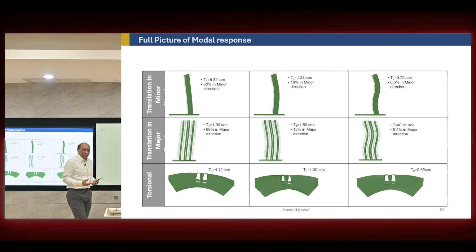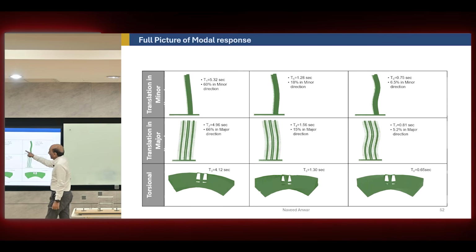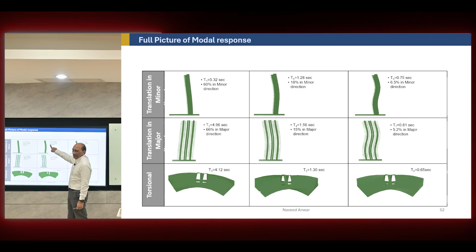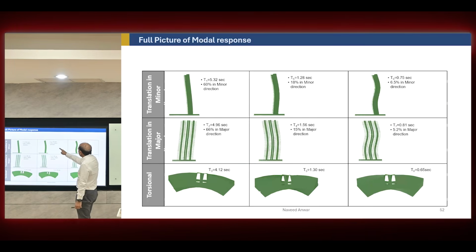That means the second minor mode is very stiff. This building has vertical irregularity somewhere. So look at the mass participation now, it's 18%. Drop. Total should be 100, about, for all the modes, 95, 90%. Now jump to the next mode, T9, 6.5%.